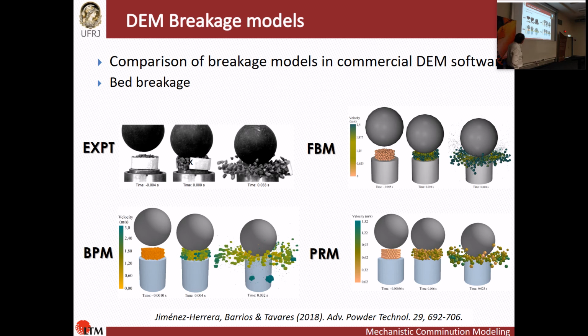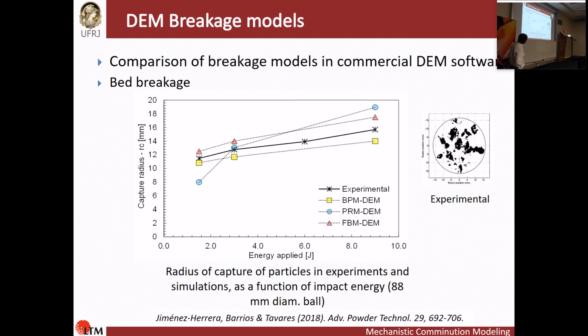But on the basis of doing this, we started doing some tests. And here you see breakage tests of real copper ore particles. And then looking here, the same configuration as the computer. It was reasonable. We did a lot of measurement calculations there. But for instance, one measure that we did is how much the bed left an impression on carbon paper. It's a good idea of how much actually it squeezed the bed, how far it applied stresses.